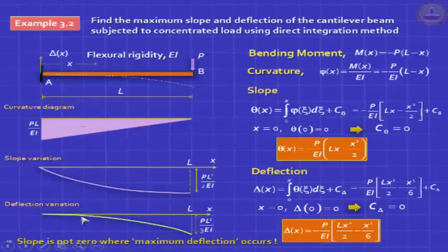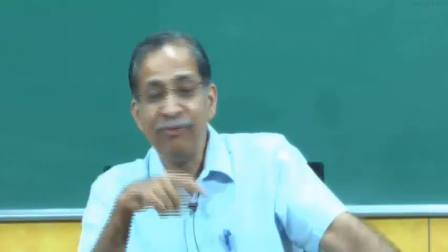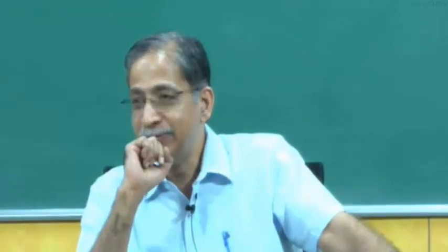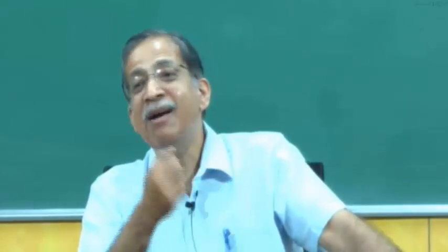this line doesn't have a point of contraflexure. So this curve will, if you extend this line, it will go on increasing. So the word maximum mathematicians use is different from the maximum that laymen like civil engineers use. So probably mathematicians will say maximum you should not use here. You could say largest deflection, which is correct, because this doesn't have a derivative which can be 0.